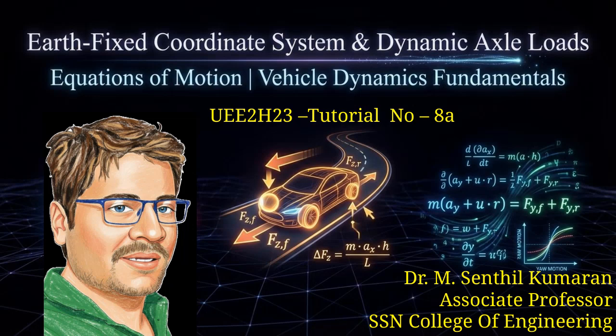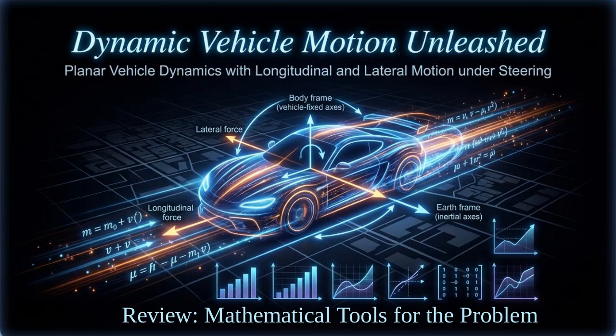Now let us begin to solve problems on vehicle dynamics. Let us discuss a problem on vehicle motion with steering. In this problem, we study a car treated as a rigid body moving on a flat road. The vehicle is acted on by traction force from the wheels, aerodynamic drag, braking force, and rolling resistance. At the same time, a constant front wheel steering angle causes the car to move in both the forward and sideways directions. This creates coupled longitudinal and lateral motion, meaning straight line motion and turning motion happen together.